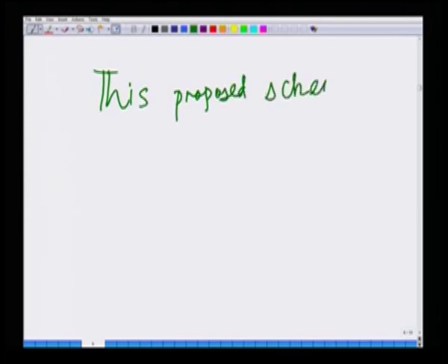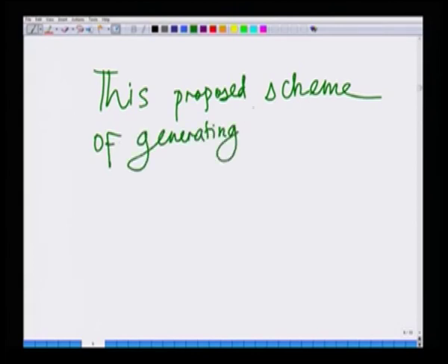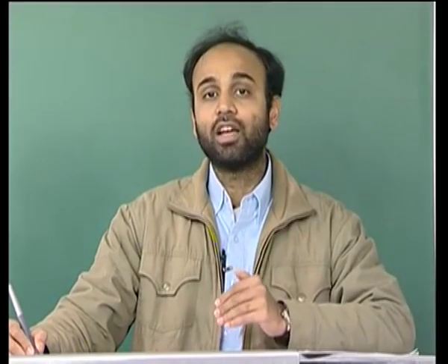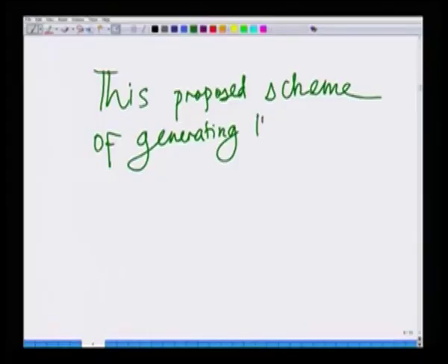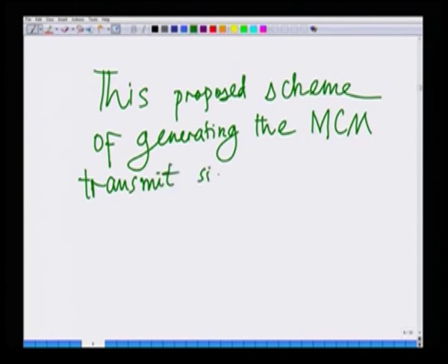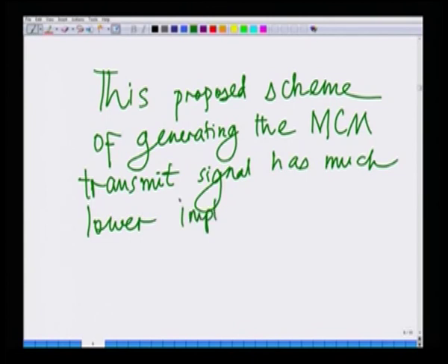This proposed scheme of generating the transmit signal by using IFFT has much lower implementation complexity than using the bank of n modulators for generating the MCM transmit signal.